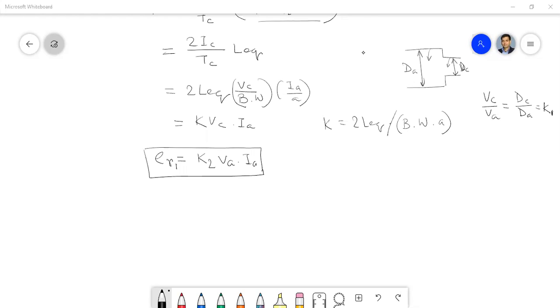In a DC machine, we generally get the rotational EMF, not the transformer EMF, as the flux doesn't change in time. But the rotational EMF we get in the coil should not be developed in the coil which is going under commutation. That I will explain later.